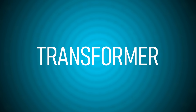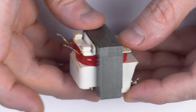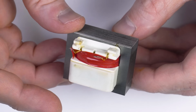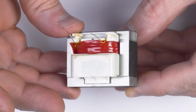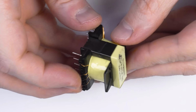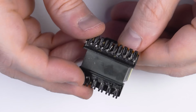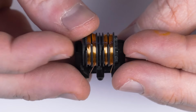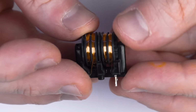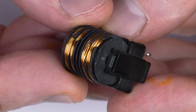Now let us talk about inductive components. That's basically transformers and inductors. These devices are pretty simple by design. They consist of one or more coils of wire, called windings, usually centered on a ferrite core. Some transformers are oval, and some are rectangular. Some contain only a few turns, while the others, depending on their purpose, may have several thousands.